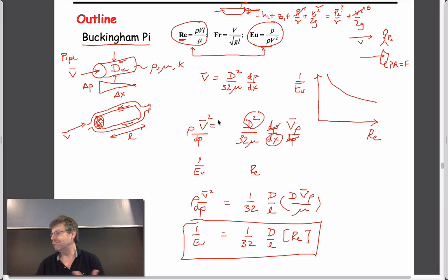And so you might say, why do we care about dimensional analysis if we know exactly what the behavior is? Well, this expression is only true for what we'll refer to as laminar flow, where the laminae of the fluid slide very nicely over each other. There are no turbulent eddies in it. But the fundamental parameters of Reynolds number and Euler number are still appropriate parameters, even when we have much higher velocities and turbulent flows, in which case we can only get the true results by doing these experiments rather than relying on the simple conditions of this simple equation. So it's an incredibly powerful technique.